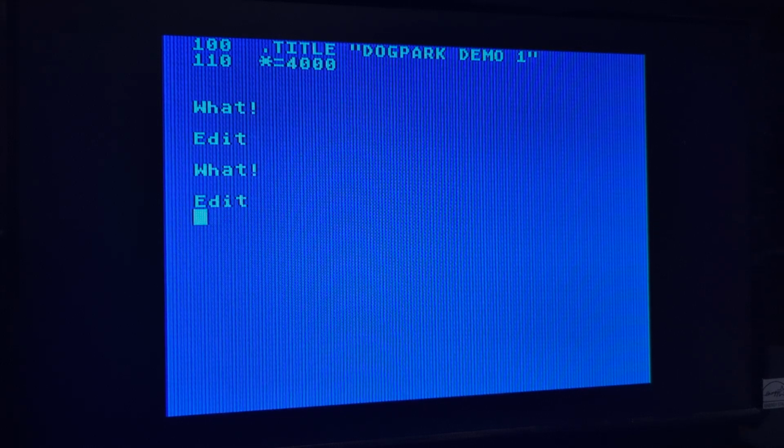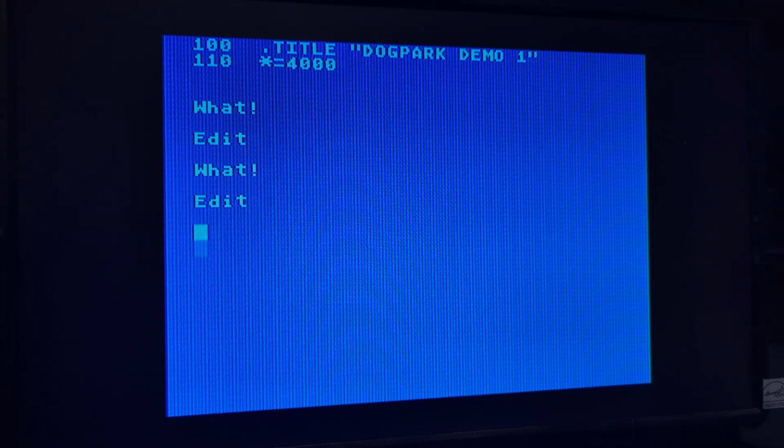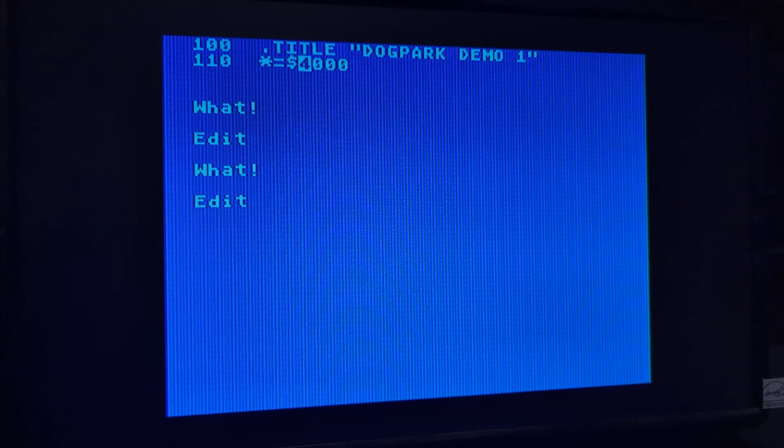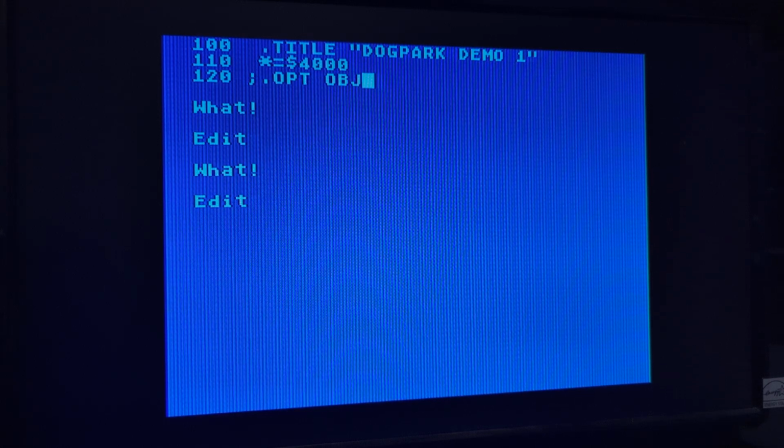So tonight, I'm going to remember that I wanted to start at hex 4000. I'm not going to forget that. And when you're doing things for the first time, comment this out so your first assembles won't assemble to memory in case you mess something up, like, for instance, starting it without the dollar sign.